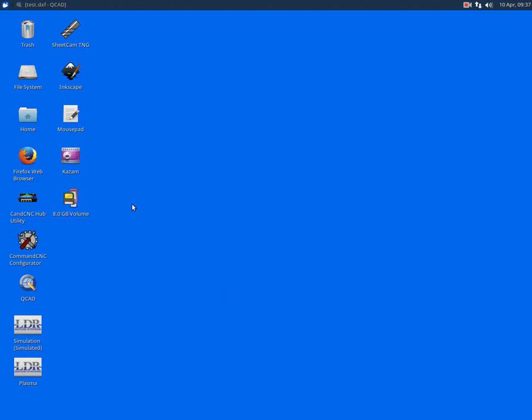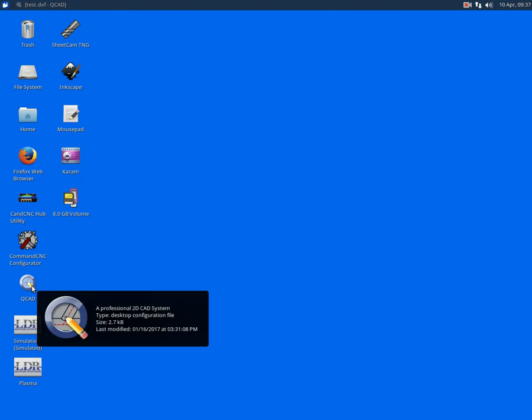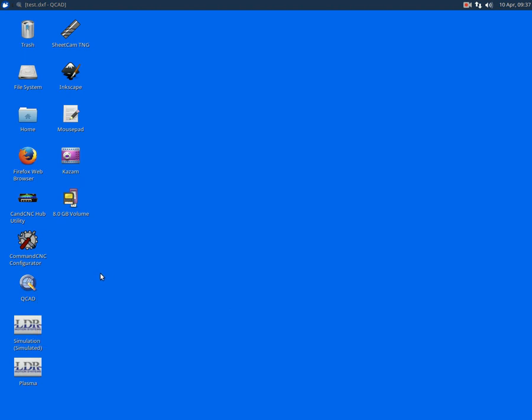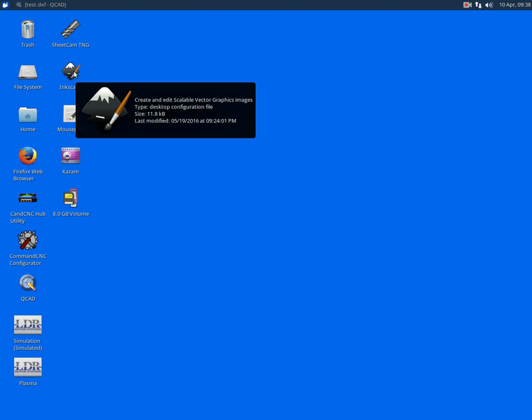Okay, once you have a drawing either generated on this computer that we supply with QCAD or any other computer that you have, save it to a USB or network through, save either SVG or DXF. We use DXF for any mechanical stuff, which we draw on either QCAD or on another computer with AutoCAD, Windows computer. And we use SVG for anything done in Inkscape, which is for us typically artwork.